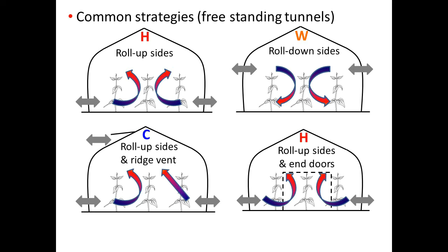For the natural ventilation and the thermal buoyancy effect, so only really on wind still days and situations, the vertical distance between the opening and maybe an outlet matters. So if you look at the third picture where we have an outlet in the ridge, that vertical distance is really determining the rate of ventilation. But as I said, most days will have some wind, so the wind effect will be the dominant force, and then the pressure differences that wind create will push the air through the structure.